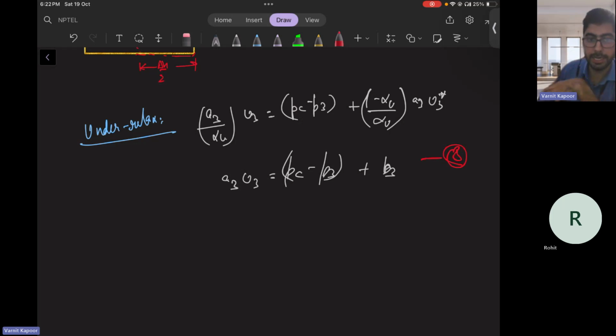So now equations 6 and 8 we have derived before. These two equations relate the boundary pressure to cell pressures. Okay? Boundary pressure to cell pressure with boundary velocities. That means we got a relationship between the boundary pressure, cell pressure, in relation to the boundary velocity. And these are required in order to update the face pressures from the face velocities that are given, and the cell pressure that we would calculate.